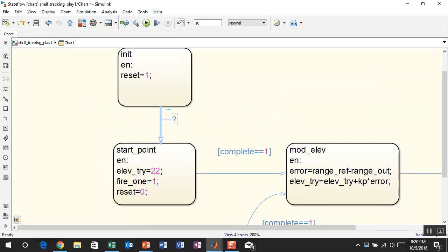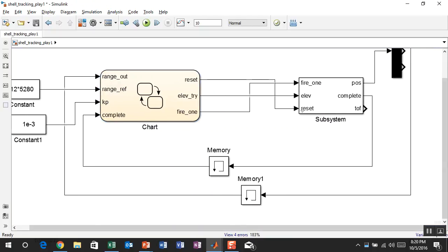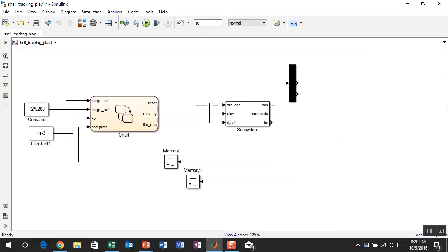One other thing, because of initialization stuff, like the initial condition coming in, I want to make this after 1 sec. And that's going to look at simulation time. So that's just going to say, don't do anything for the first second of simulation, and then you can act normally. Because that way it'll give things a chance to initialize themselves. Alrighty, so we are now ready. So let's turn this thing on.